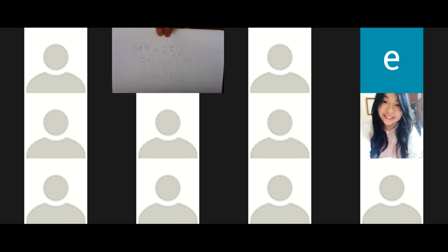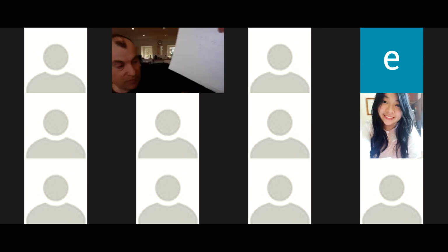What we need is the general rate and a little bit of leeway. We add on 25%. And the way to do that is that we multiply the greater of the two numbers we worked out earlier, 39, by 1.25. And the answer is 49 litres per second.